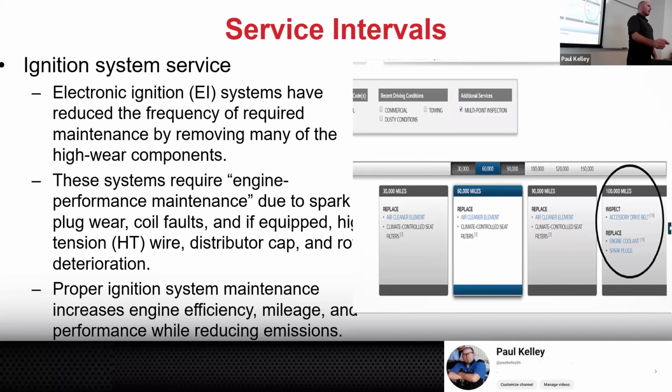Now, if I diagnose it and the coil's no good and I replace a coil, I really should replace the spark plug that was associated with the coil, because that spark plug's going to be all fouled up because it wasn't sparking, it wasn't burning. If I'm going to do one spark plug, I'm probably going to do four, but then I'm going to weigh in when they are due and when they were done. You know, there's some things to weigh out, right?